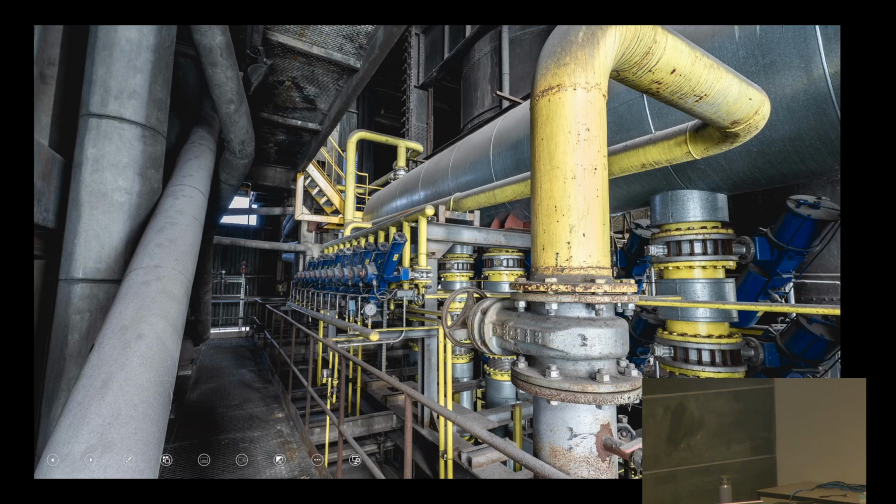You can generally tell valves apart by their handles. So this is a quarter turn ball valve. It will open completely in a quarter turn like that. So when it's like this, that's closed, and when it's like that, it's open. The gate valve takes a lot of turns to open, as any plant operator knows.